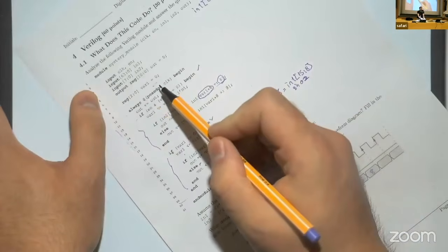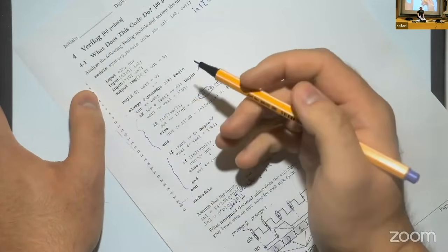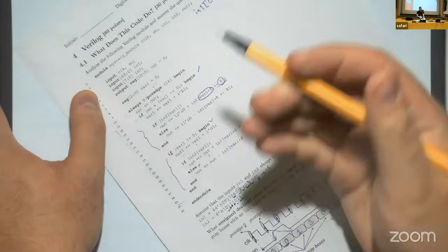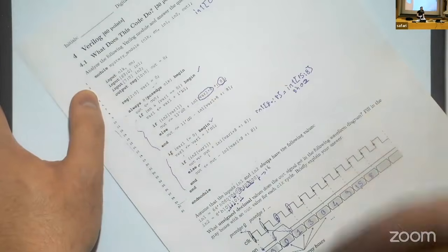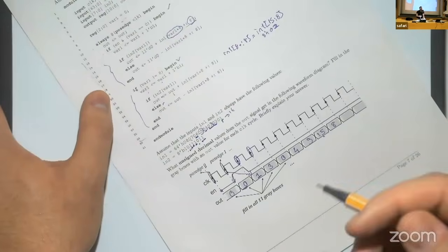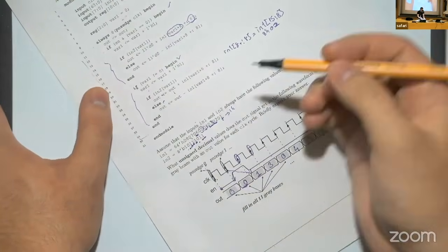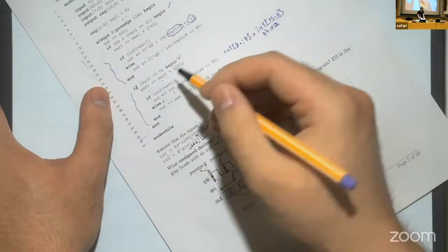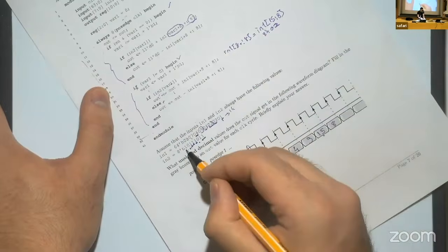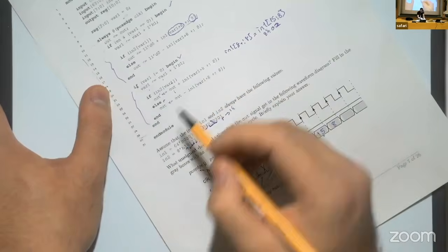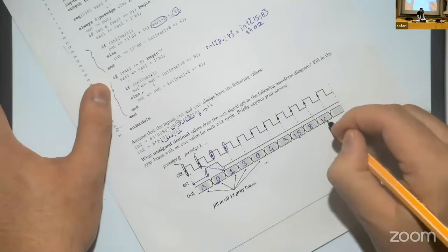But the problem here is var1 is 3 bits. So 8 is actually 4 bits, right? 1, 0, 0, 0. What happens is that var1 takes the least significant 3 bits, which means you reset var1 to 0. So in the next cycle, var1 becomes 0 again. Let's execute this cycle. Where var1 becomes 0 here, we check the 7th bit of in2, which is 1. Then we perform addition, 8 plus 8, which is 16.